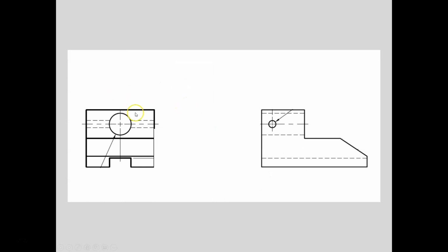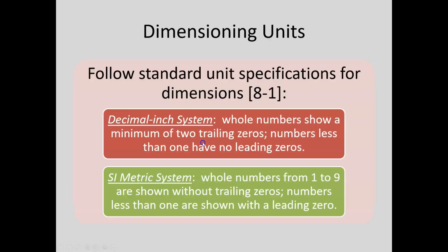All right. Here's another problem for you to work on. So again, try this. If you really want to practice, you can sketch this. Sketching is a good skill to have, and you can practice your sketching of this. If not, you can just print this page, and then you can try to use our 2-step dimensioning procedure. Dimension 1 for size, 2 for location, and then include your standard symbols and notes. There's your answer.